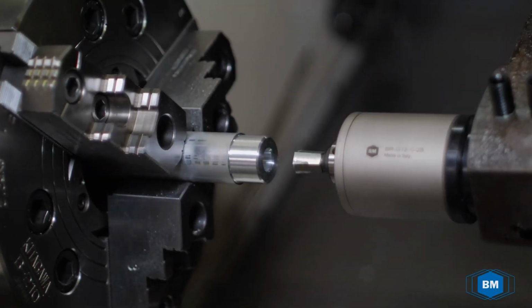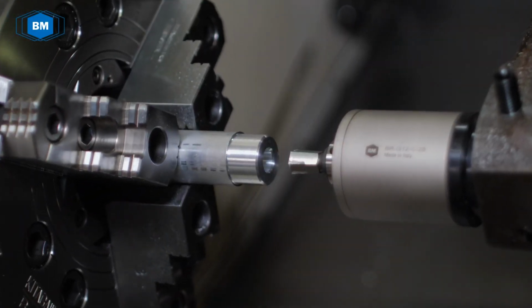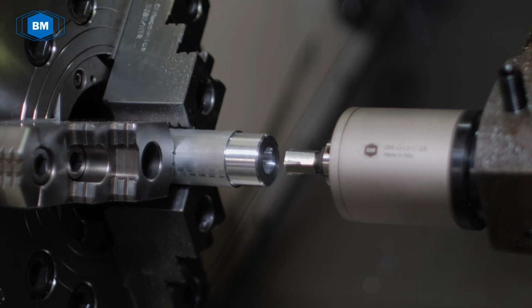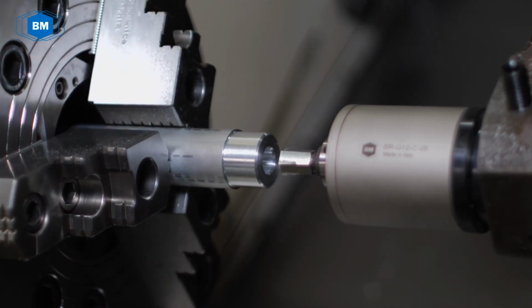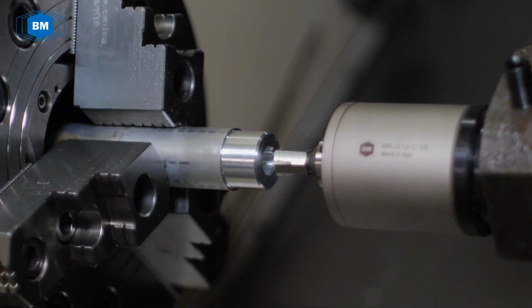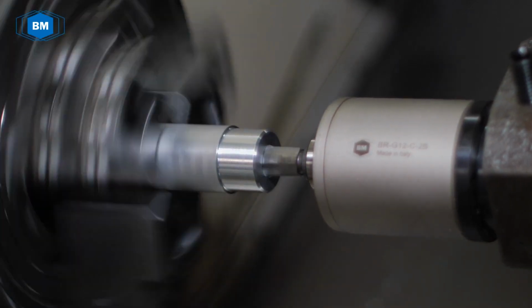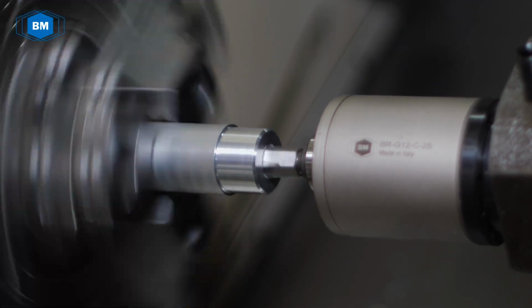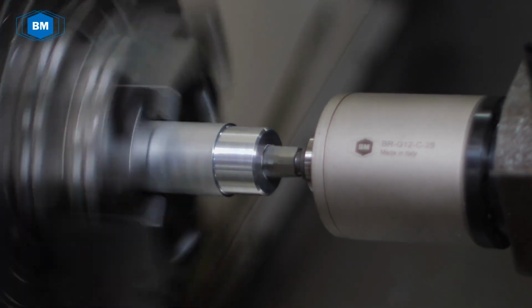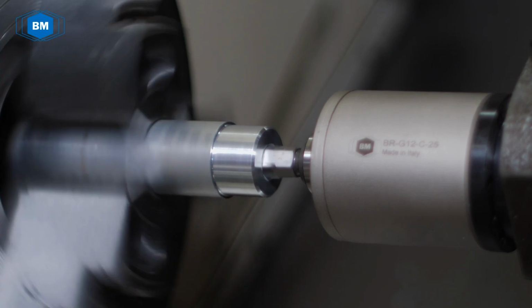Once the pre-hole has been performed, and, important thing, without having to carry out shooting operations, proceed with the approach of the broach to the pre-hole of the closure cap, which is in a static position. The choice of rotation speed, most suitable for a correct broaching operation, refers to the parameters of use for machining with HSS and sintered broaches.